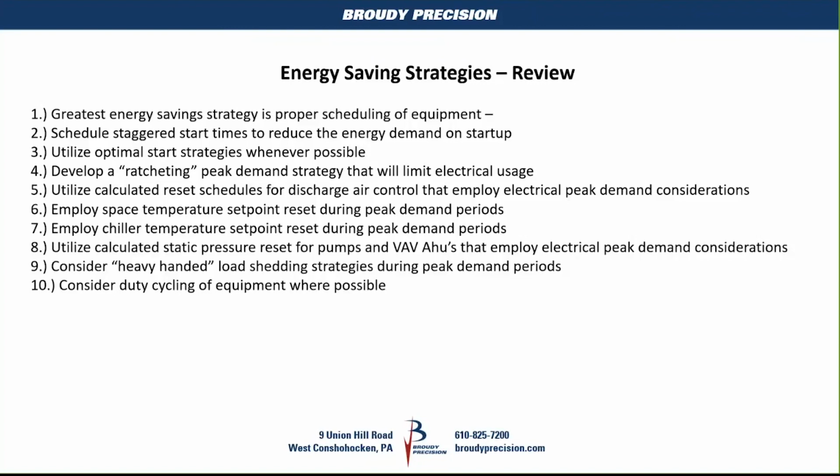But with modulating service, if I calculated I need to maintain 55 degrees because my space is hot, what I can do is essentially take this peak demand information that we've calculated, because we're getting into a high demand situation, and we can add that number to the tail end of our reset.